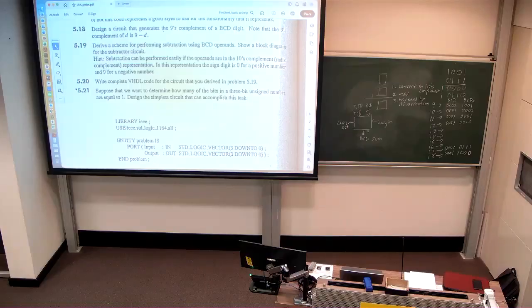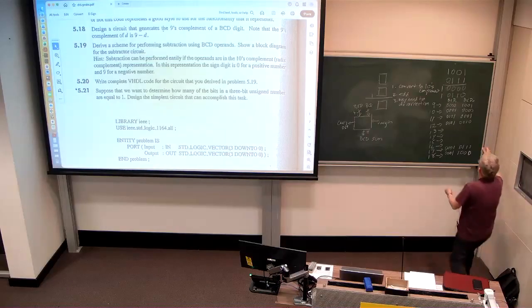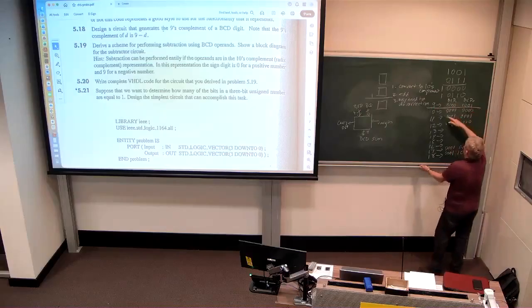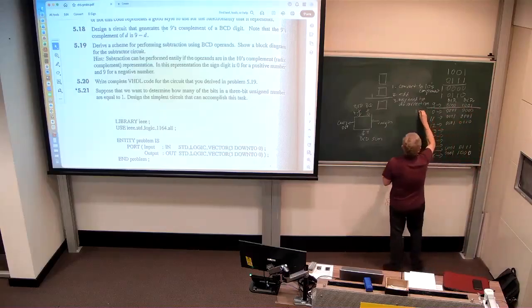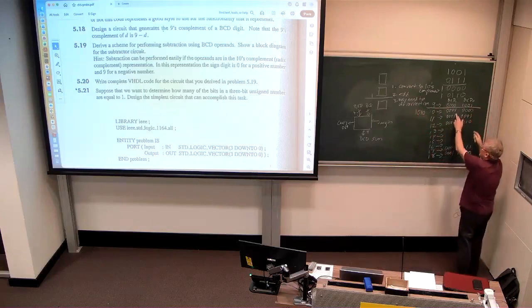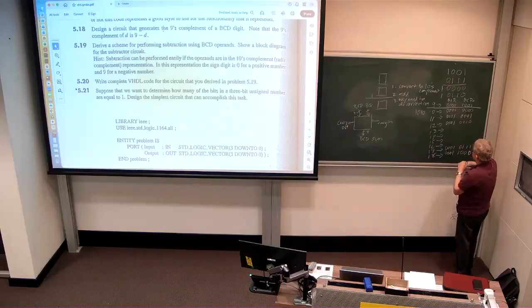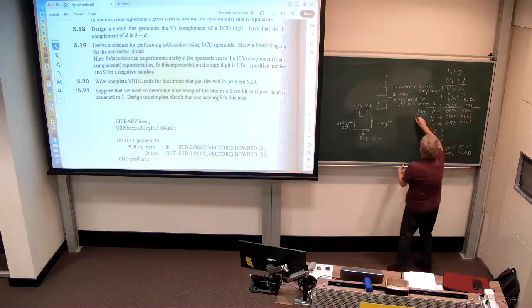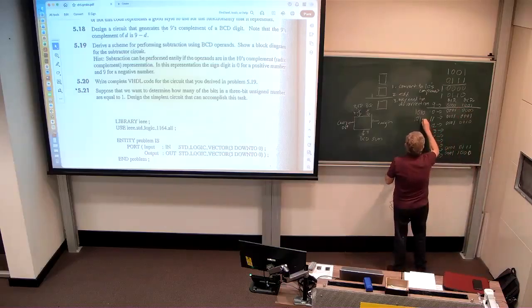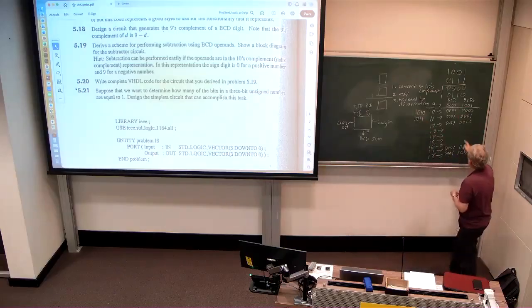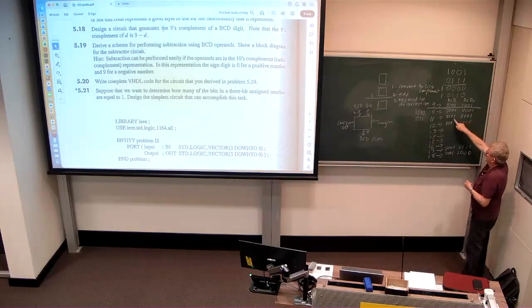But if the sum is 10 or more, we have to do a conversion, right? So we only have to worry about these results here. So effectively, 1010 has to be converted to 0, and we have a carry out of 1. This is our carry out bit here. 1011, so 11, has to be converted to 1 with a carry out of 1.